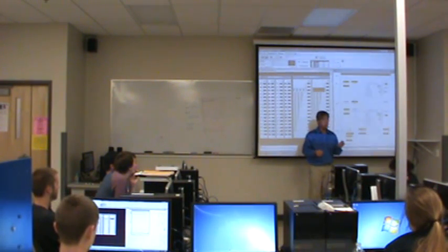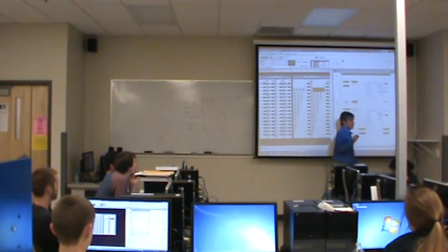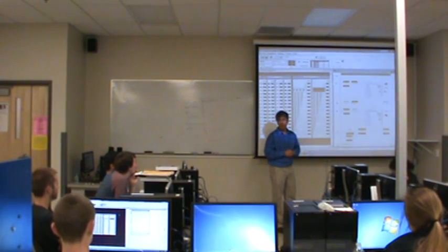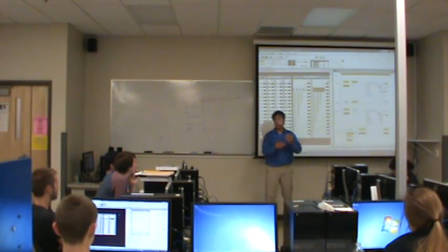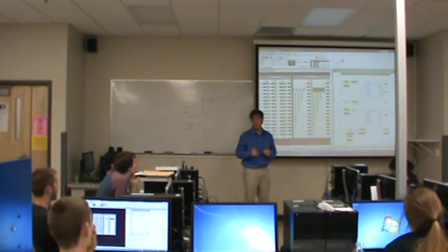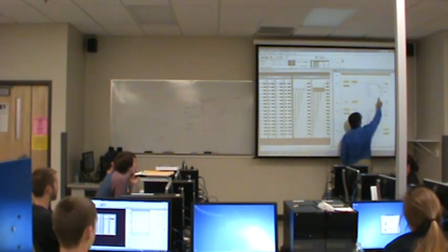Now, it may turn out that you want to look at inputs, but you don't really care about some of the inputs. There's only 2 or 3 in there that you really care about. Maybe you've got a PLC where you've only got 1 input card, you've got 16 inputs. There's only 2 or 3 of them that actually drive the sequence. In that case, what you can do is use what's called a mask.